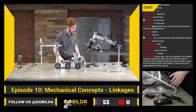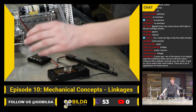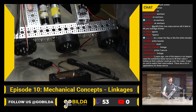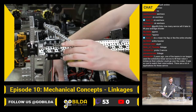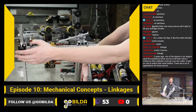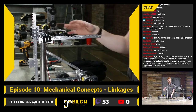You can take a look at how this linkage works to get an idea of how you would implement something like this. Basically, what you're going to want to achieve is, when your claw is clamped down on something, to have the two arms of that linkage be parallel. In this case, if you push on the end of this system, it's going to take a lot of force to be able to backdrive that servo, and that's a really, really nice application for it.